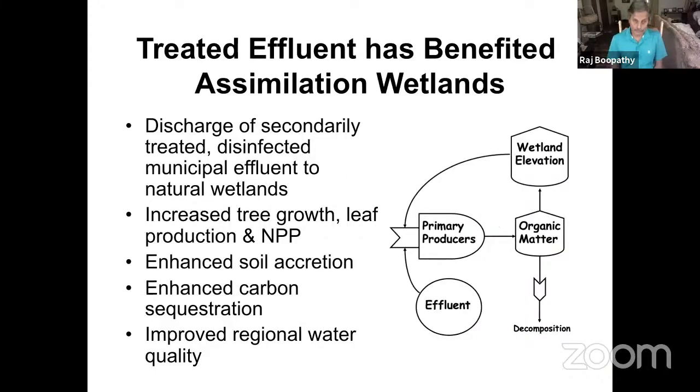Another thing catching on in the US is the wetland. So this is, I'm involved in locally, we call assimilation wetland. So when you discharge the treated wastewater, your regulatory standard is really a little loose, because the wetland is your final polishing step. So your COD, BOD in your wastewater could be high, and solids could be high, but the wetland will take care of your final process.